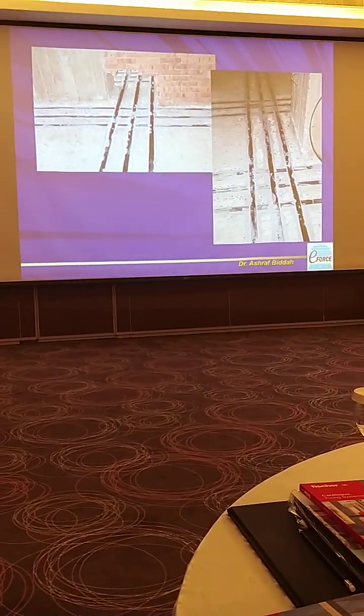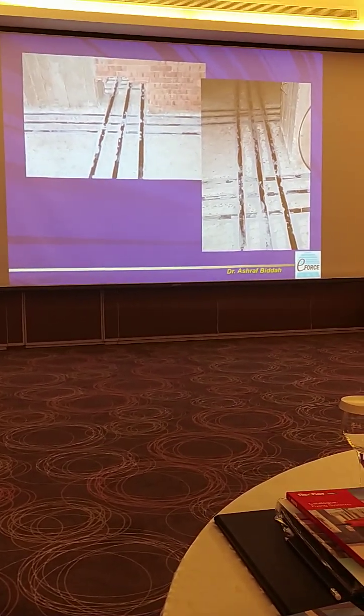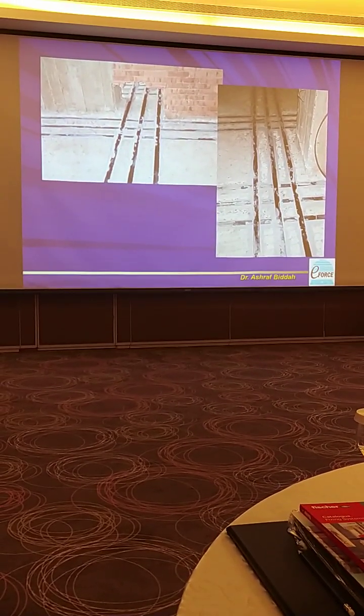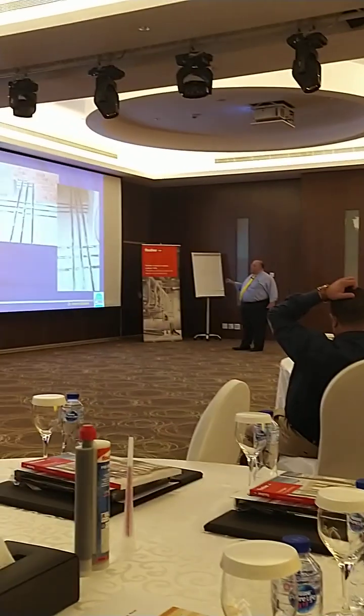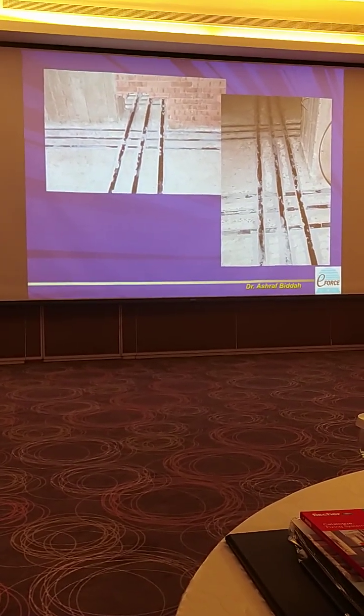Because if you apply it and imagine that it is working, but it is not working, then you did nothing. So it's very important to assure who will apply the CFRP. And the other 50% is making sure the concrete surface is well studied and prepared. The surface preparation in the area where you apply the carbon fiber must be accepted. You will put enough of the specific glue that comes with the CFRP as one unit.